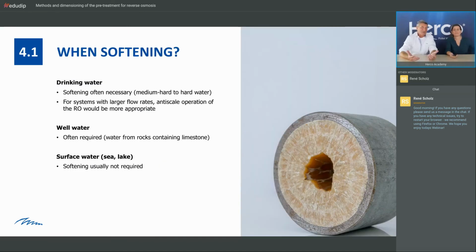So I think for drinking water it is normally always necessary to have a softener, because of the reverse osmosis, you remember this one. You have there in these really narrow channels the problem not only that the feed water contains something which could precipitate in these small paths. You also have a concentrating process in the RO, and that's the problem. You have 4 times, 5 times, sometimes 10 times the concentration of the initial feed water, and that's why this hardness is a really hard problem.